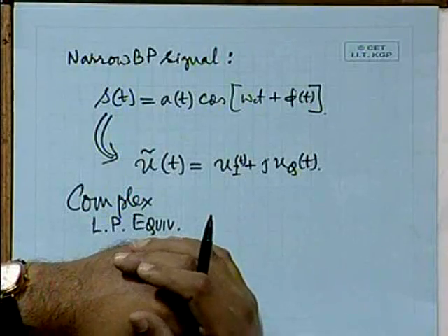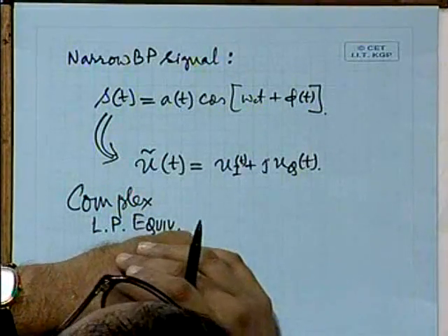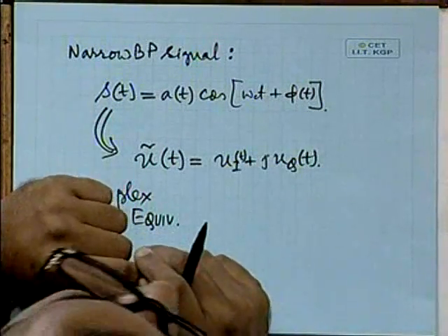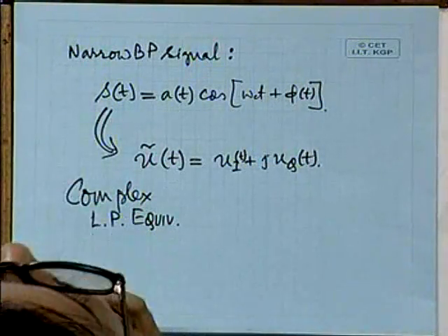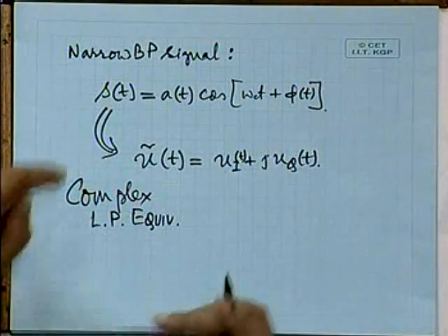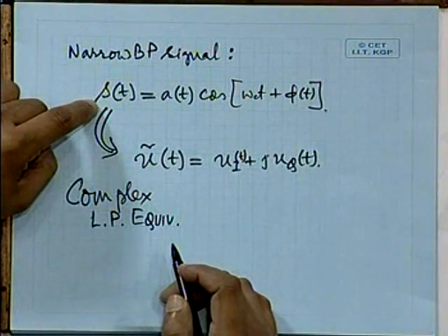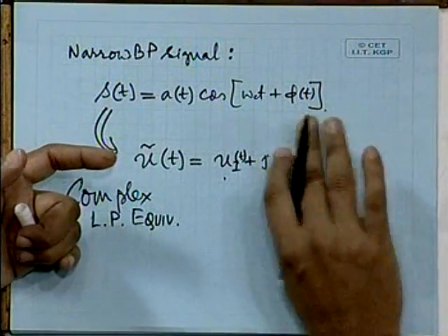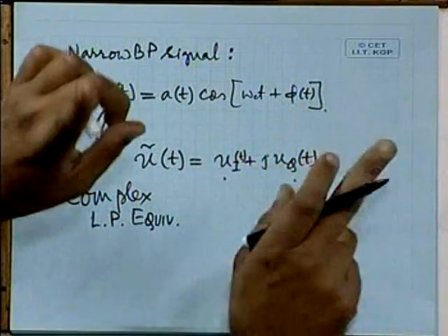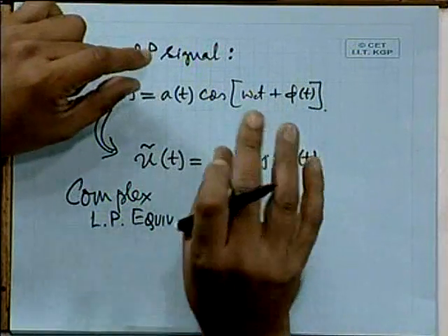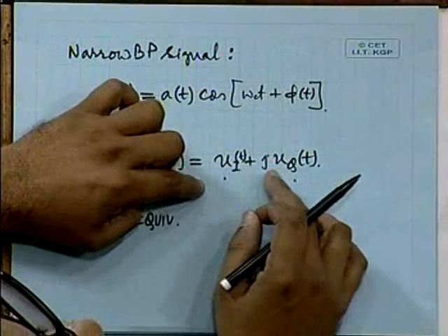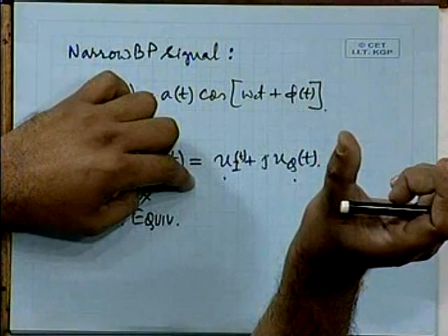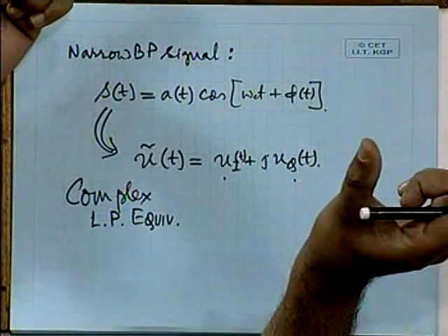signal constellation, where the dimensions phi 1 and phi 2 were related fundamentally to cos omega ct and sin omega ct, and then the signal s of t was viewed as ui and uq t, weights of the corresponding dimensions of cos omega ct and sin omega ct. Now if I express it in a somewhat different manner with scalars such that the cos omega ct portion has got unit energy over the symbol duration of T, I can do it very well.